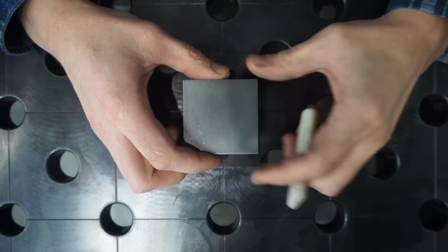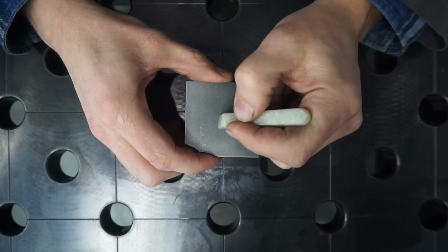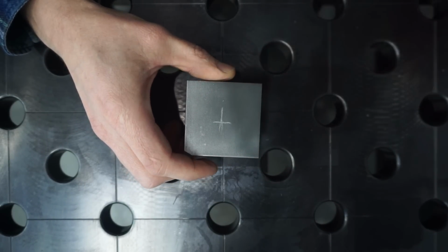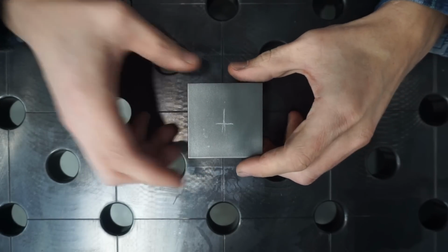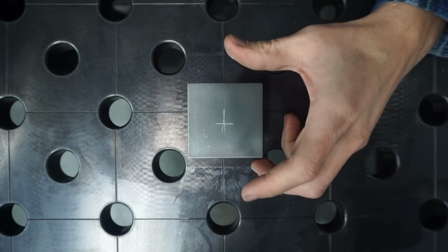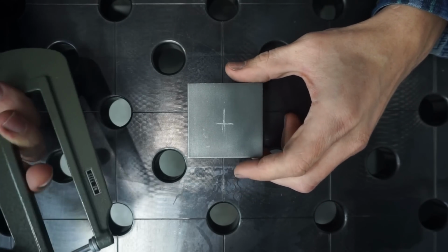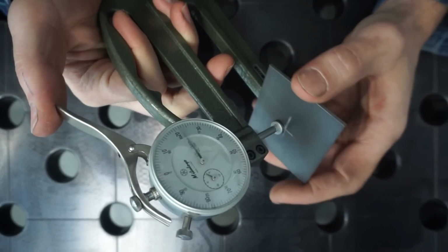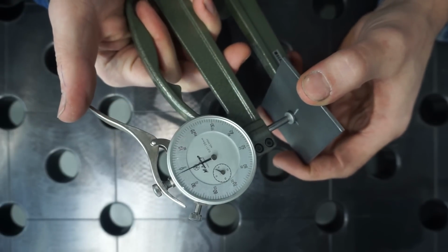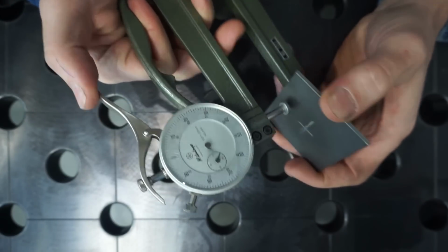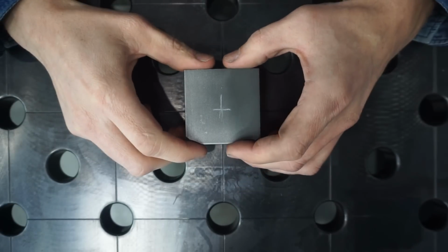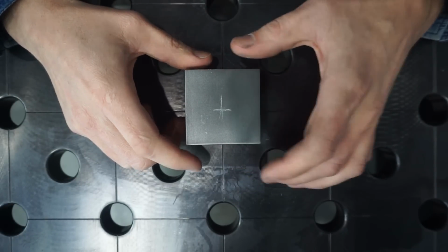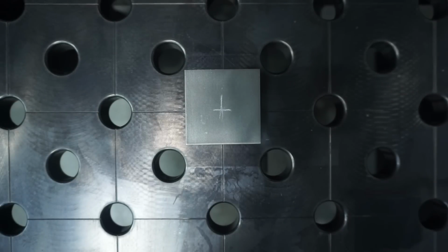Next, let's do the same as in the very first case. Place a heated spot in the center of this sample here. Except that this time we evenly preheat the sheet to, well, let's say a blue tempering color. Initial thickness here is 2.98 millimeters, and after preheating I'll try to heat the heated spot to the same orange radiant heat color as the first one.